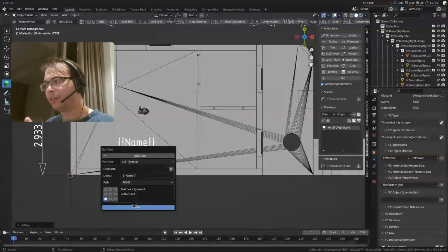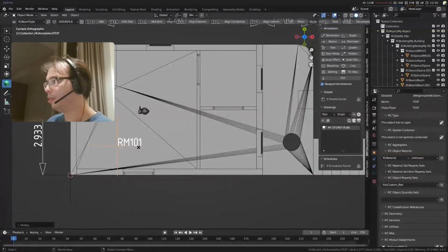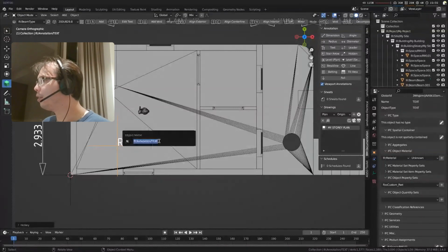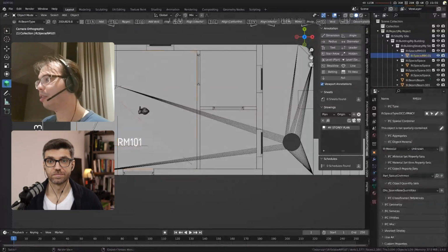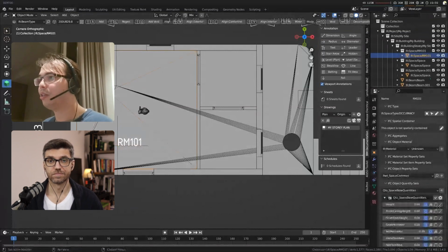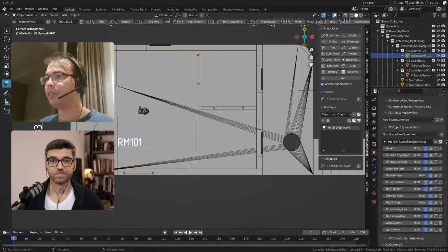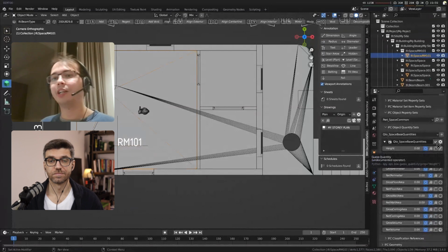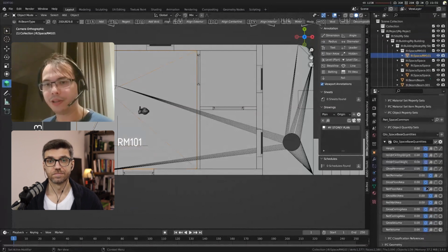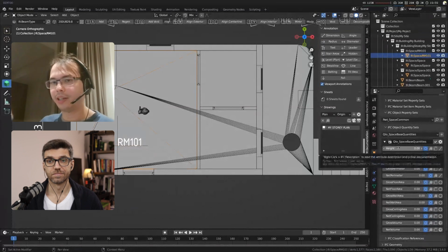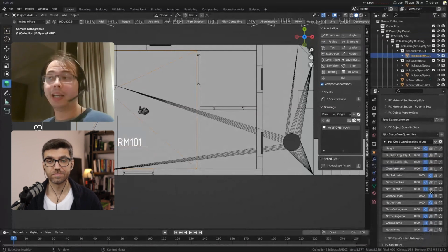At the moment, you can see there's a few clicks involved, but this will get in 2 weeks when this is released. Is it 2 weeks? 3 weeks? When the next release is out, this will be tagging as you expect it to be, tag, tag, tag. But here's the manual approach right now. I say it's related to this space. So now there's a semantic relationship. The tag knows it's related to the object. So now I can start using variables in it. I can get the name, for example, and now it knows it's tagging room 101 intelligently, right? If I change that, it changes the other and so on. So that's the manual click, click, click, link up the two. Hopefully that makes sense.